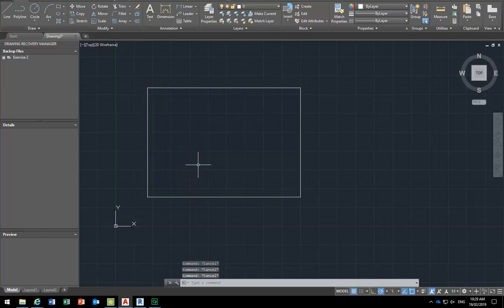Sometimes you'll just forget. I still do it. I'll forget that I'm in the layout, because often you will be drawing on your layouts, but in a viewport, and then you'll forget sometimes that you've switched back to paper, and then you might have drawn quite a few things. If you're doing a detail, you draw a lot of lines in, and then go, oh God, I want all those lines, but it's in paper space. So you can always take that back to model space if you have to. But worst case, if copy and paste isn't working for you, you can always W block it. And it's good to know that.